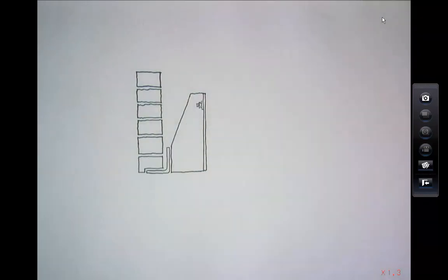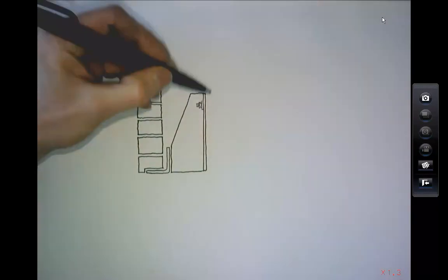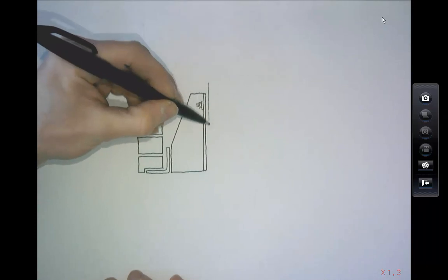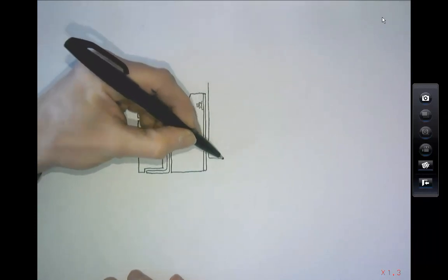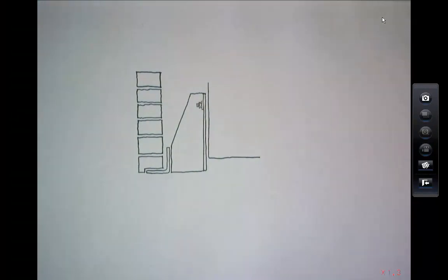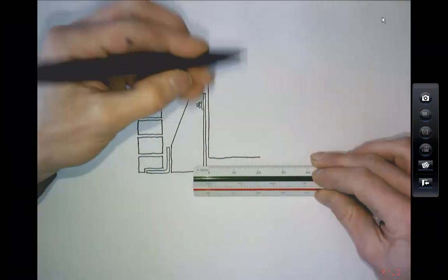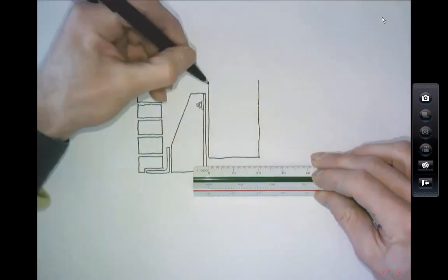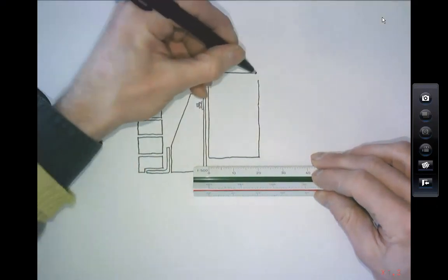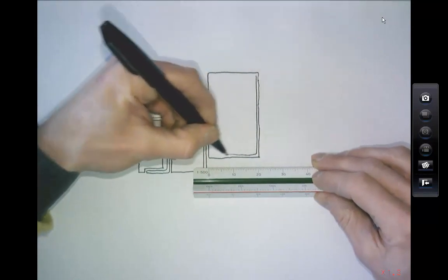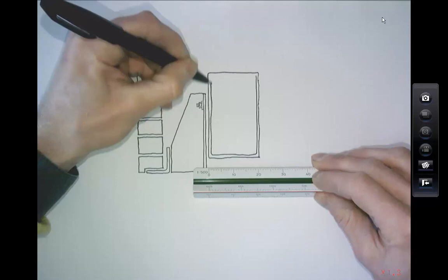And normally, to be honest, the best way, if you're doing a steel frame, is to make sure your structural engineer gives you a rectangular hollow section. So a box section. And that's what we did here.